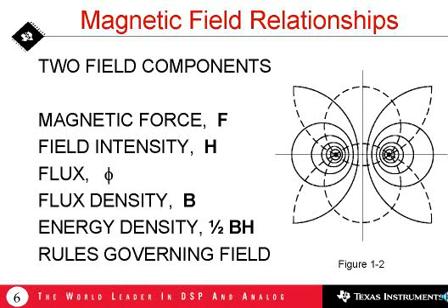If the 2 conductors were far apart, the magnetic field surrounding one conductor would be so weak by the time it reached the other conductor that it would have no effect, and then we would see a perfectly symmetrical radial magnetic field surrounding each conductor. But when the 2 conductors are brought close together, as shown, the fields interact to result in a stronger field between the 2 conductors, and the field components subtract as we move away from the 2 conductors and tend to cancel.